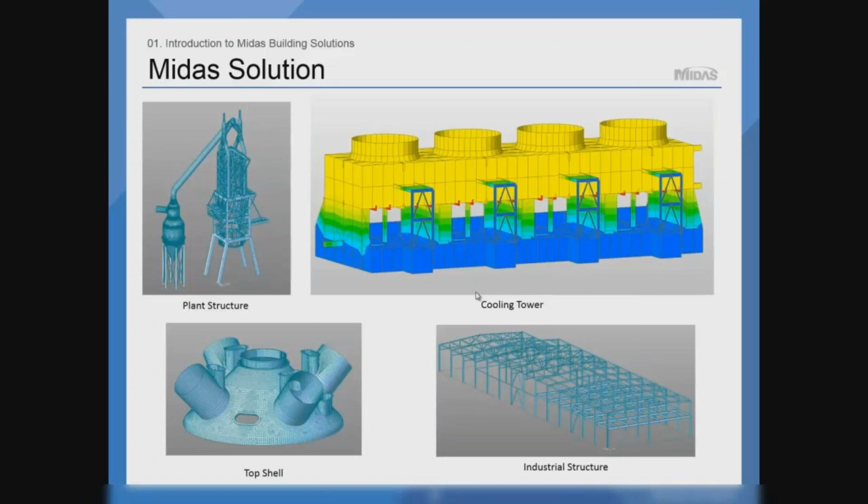Even for the trusses, we only have to click on the optimization. The program will automatically give the optimized section, or if you want you can choose it from the data table, and it will give you which is the suitable section for those particular forces. And one more thing is, whenever you see the result for the steel structure, it will give the clause number also, meaning for which clause it takes the values. So the entire thing you can get in WordPad document format. So these are the things available in Midas.